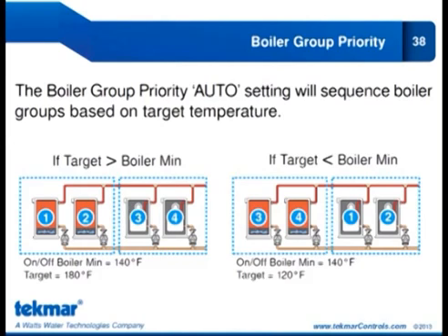So again, you can always say the lead is always the condensing, regardless of the calculated boiler minimum, or you can have it choose based on what the boiler minimum is. That's just to capture the point there as well. On the 275, we did enhance that operation at one point where we supported this mixed plant, but with the 275, you don't get this selection. It always leads with the condensing group, always. Again, with this, you get to choose.